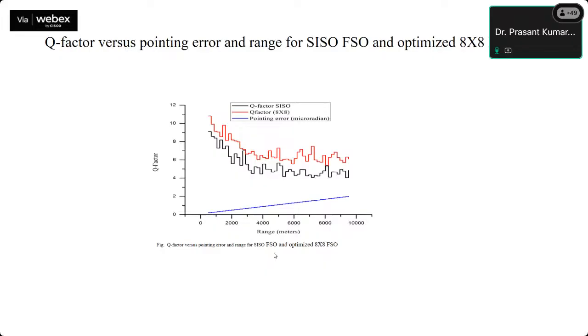And then this is the other part, what I was telling. So once we implement that MIMO systems, we observe that it is possible that we can improve the performance of the link because of this pointing error or because of the turbulence effect. So then we again analyze the system, including a defined pointing error, which is not fixed, but which is kind of variable over time.